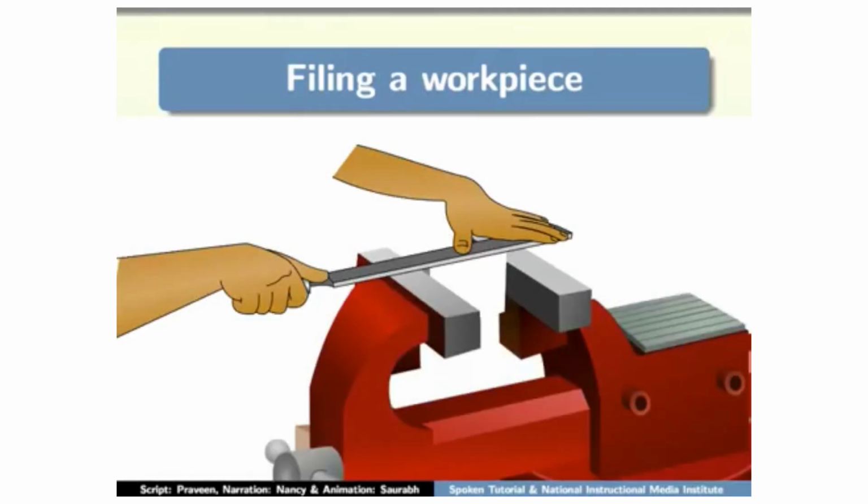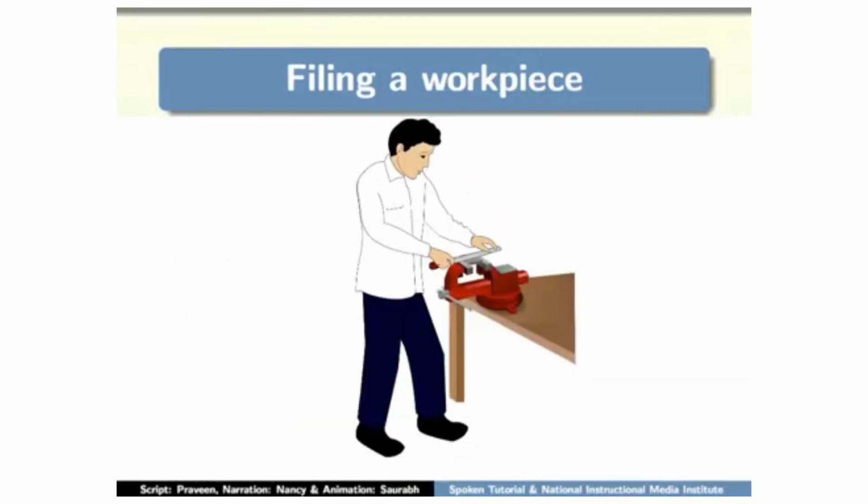Now hold the handle of the file firmly in your right hand. With your left hand, hold the tip of the file as shown. Ensure that the right thumb is pressing the handle of the file firmly. Now we are ready to start filing.